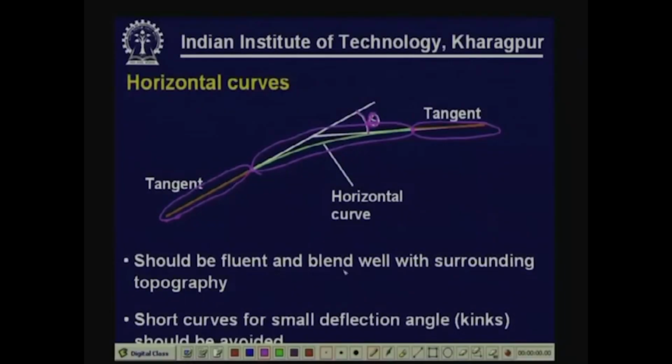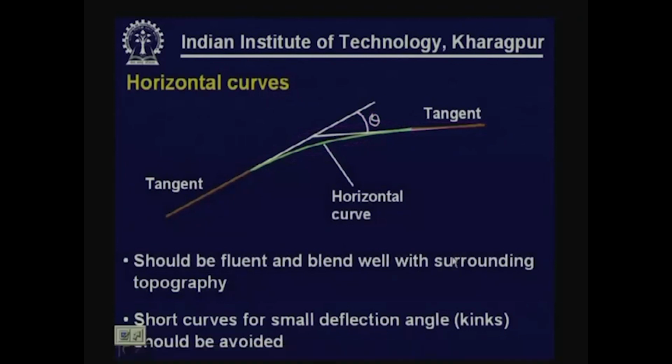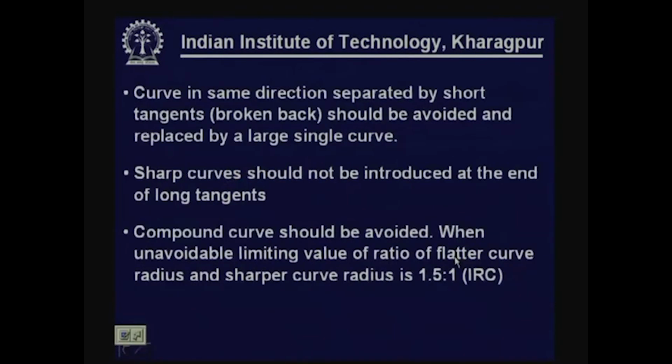Now, some of the do's and don'ts. Curves should be fluent and blend with surrounding topography, short curves for small deflection angles should be avoided, curves in same direction separated by short tangents should again be avoided and replaced by a large single curve.